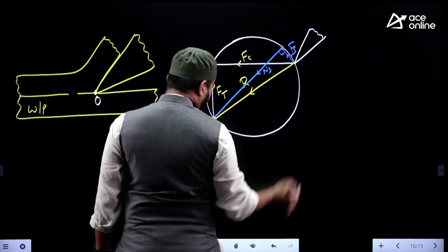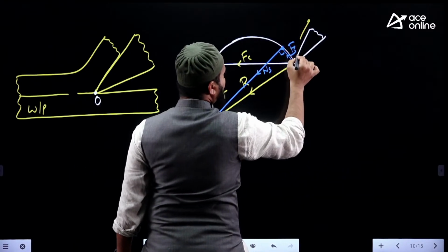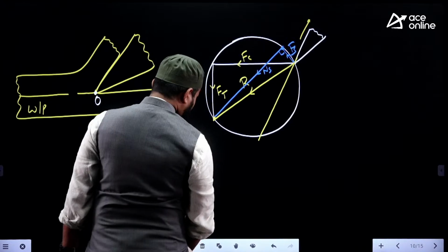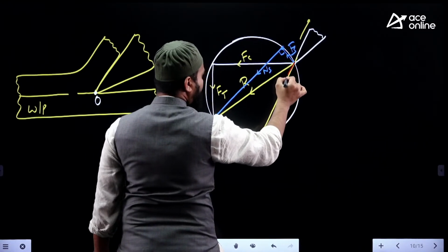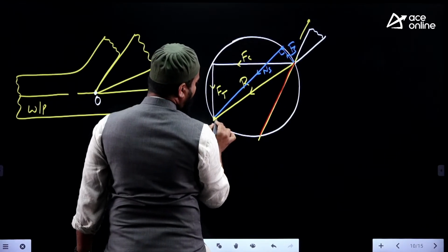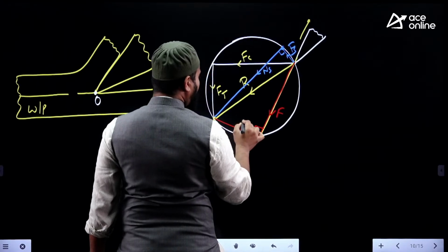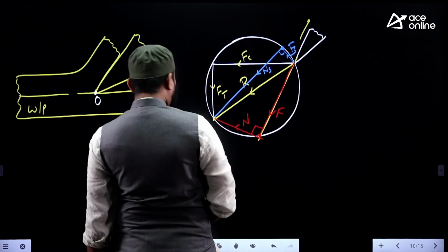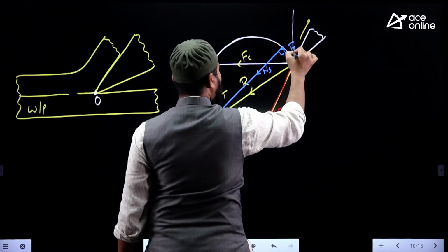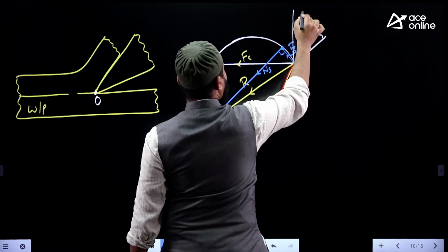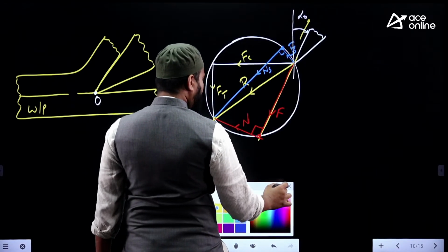And parallel to the rake face of the tool, as the chip is traveling in this direction, in the opposite direction there will always be a friction force. And then there will be a normal friction force. This is the friction and this is the normal friction force. We can give the relationships between all these dynamic and measurable forces with respect to rake angle alpha, then shear angle phi.